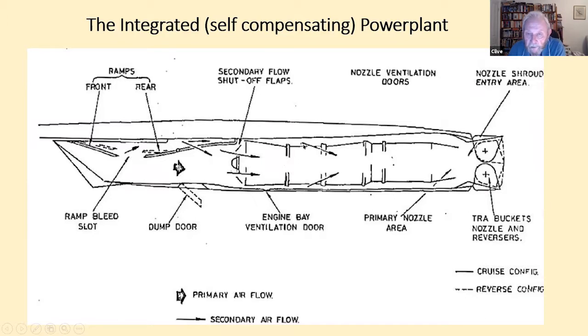Some of it might be taken off, and there might be some other bits and pieces poked in there. But at the end of that, this bleed flow is turned into this secondary airflow. So it's slightly higher in temperature, slightly lower in pressure, but it's the same mass flow as you started out with. Then you have the system I just described.